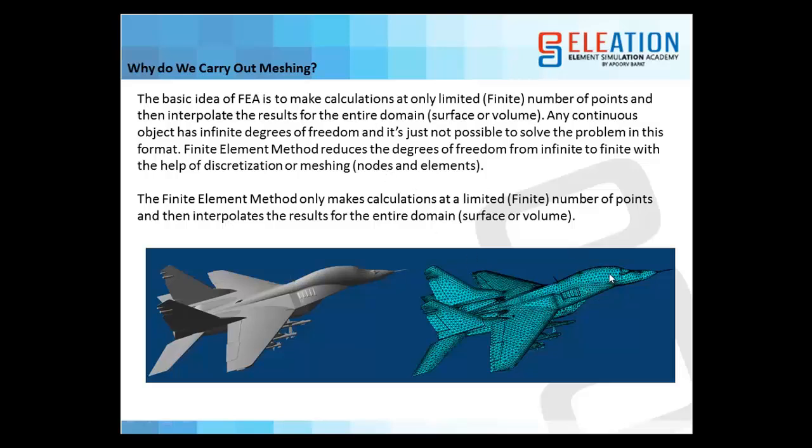that is creating nodes and elements. So we create some nodes and elements. Actually we discretize this model into some calculation points, and then the software calculates the values of, for example, stress, displacement, strain, temperature, whatever output we want on those limited number of points, and with the help of the shapes which are generated by connecting these nodes, called elements, my software calculates the results for the entire domain.